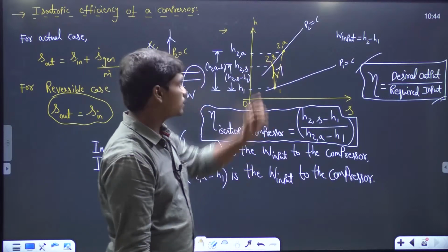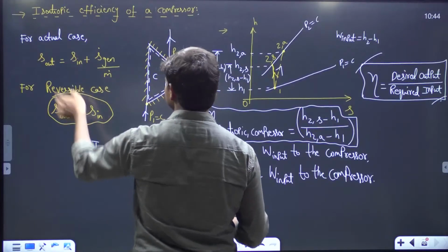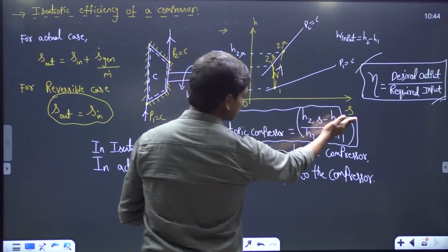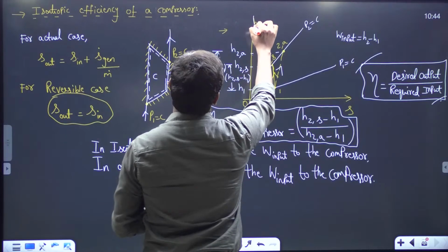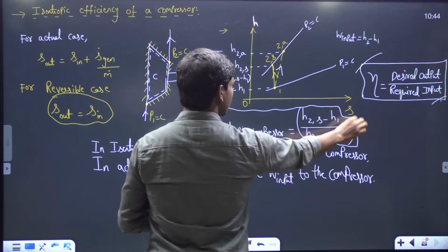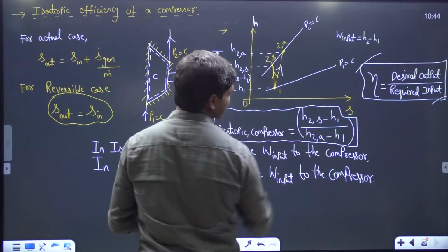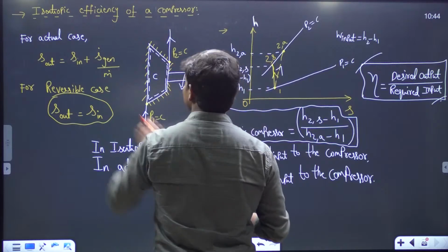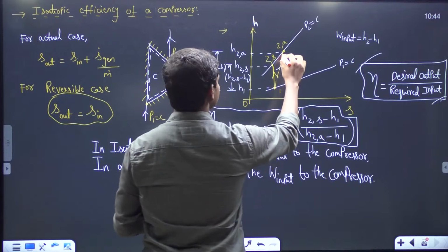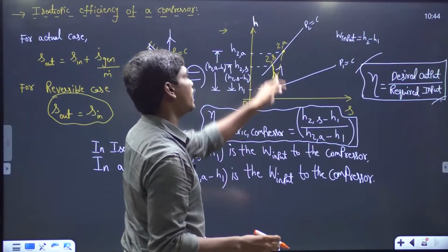This graph, Arvind, so see here, if you understand these two equations, when the case is reversible, S outlet should be equal to S inlet. It means if I want to draw a process on an HS plane, such that my initial entropy and final entropy are the same, but enthalpy is increasing, then the only thing I can draw is a vertical straight line, correct? Next, if the entropy is increasing along with enthalpy, of course this is a curvature, we'll see later, that's not part of this basic thermodynamics course. We need some advanced analysis for identifying the nature of this curve.